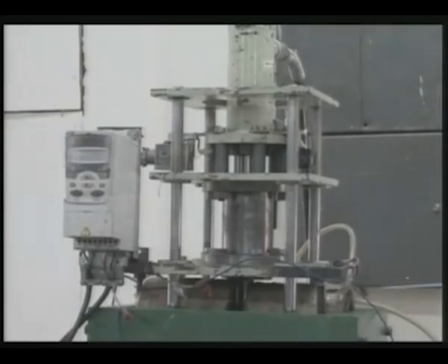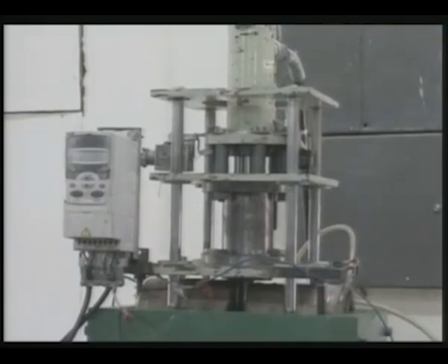The diameter of this electromagnet is 160 millimeter and its length is 150 millimeter, and it is a hollow electromagnet made of copper coil. Our coil has 2000 turns of 17 SWG copper wire with square cross section, and it can take up to 10 ampere.